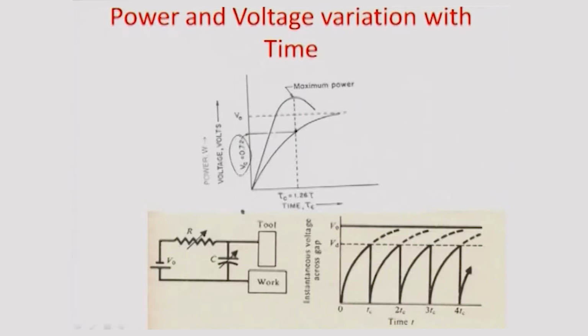The time constant of the capacitor may be somewhere here, which is 63% of V0, and it is going above the operating point here for the power graph to rise to its maximum. So, this is the power condition corresponding to dP average by dx equal to 0, x equal to 1.26.